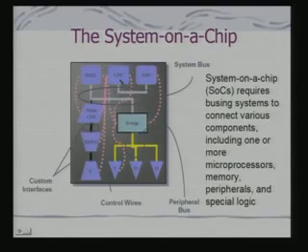So there will be a fast bus. So you have a system bus, you have a bridge connecting it to a slower bus to which this kind of input and output devices can be connected. There may also be custom interfaces. Here an example has been given for an MPEG encoder. So if I have the data, that MPEG encoder converts it, and it uses a kind of custom interface to write that data through the memory controller.